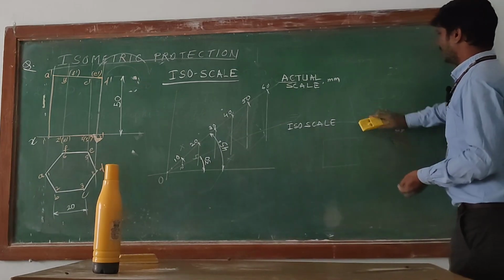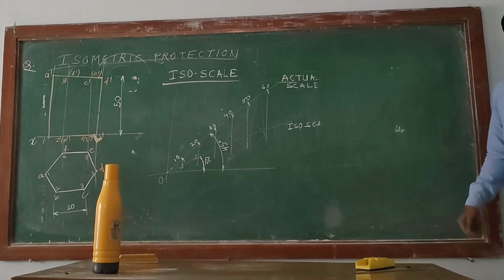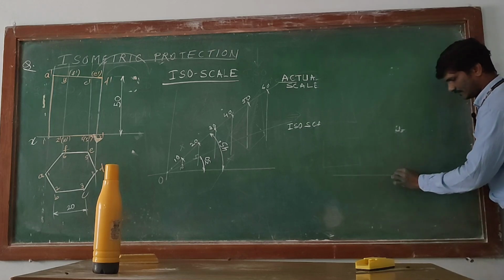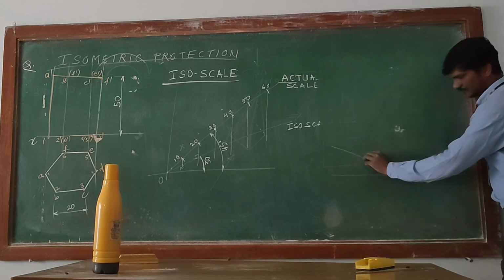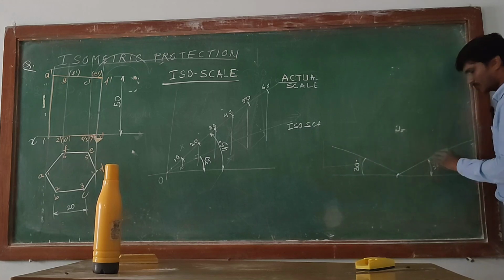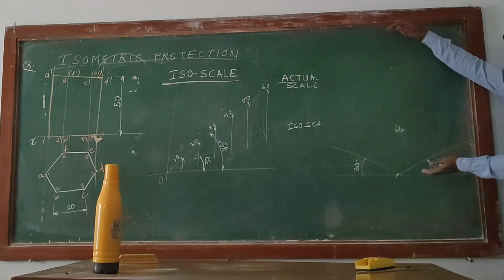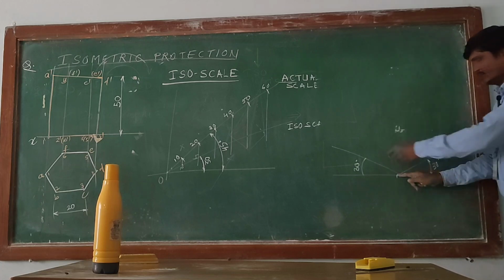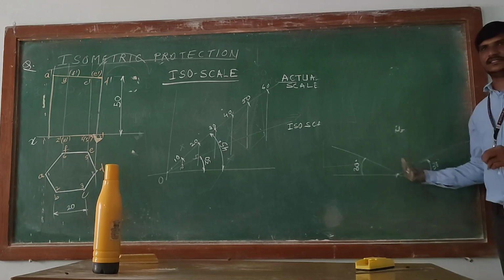After that we have to construct the 3D object now, the isometric object. Draw one horizontal line with thin lines. Somewhere draw one horizontal line, and you should have the approximate distance of 50 mm at what height it can go, it should not go beyond. Find one point on the horizontal line and make two inclination lines, 30 degrees and 30 degrees, on both sides.